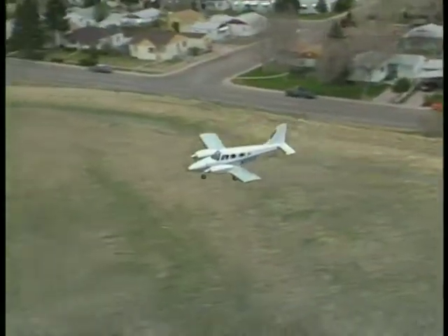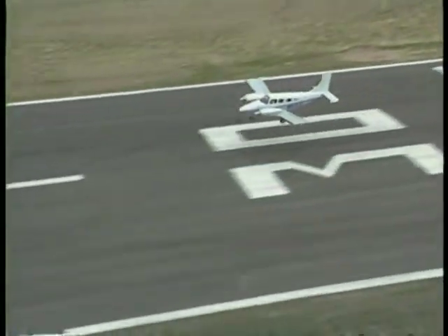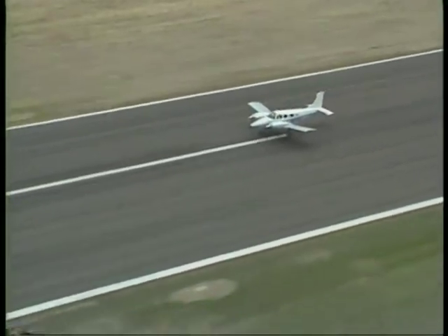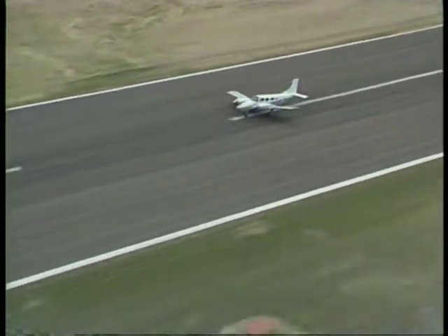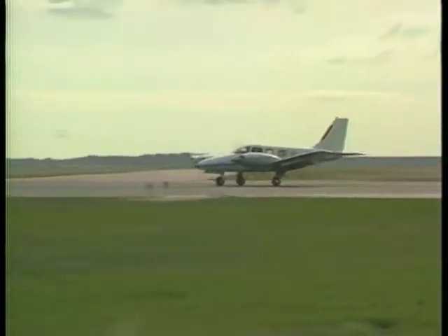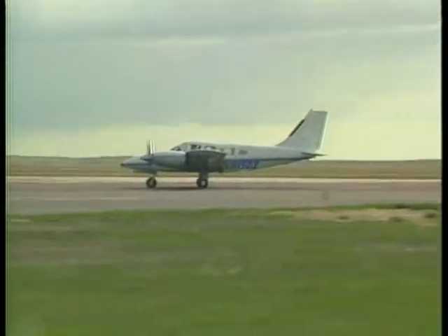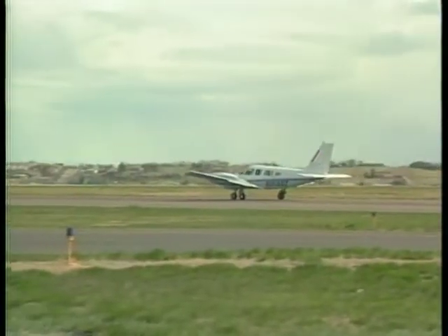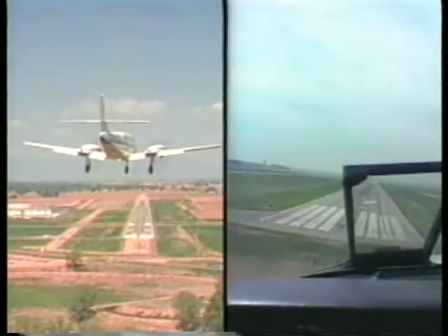As you approach the runway, make a smooth transition to the flare and slowly retard the throttles to idle. Remember that a rapid reduction in induced airflow will cause an immediate loss of lift. During the first part of the landing roll, use rudder and nose wheel steering for directional control. If runway and traffic conditions permit, avoid using the brakes until the airplane slows down. For a crosswind landing, whether you use crab or the wing-low method on final, make sure the airplane is aligned with the runway before touchdown.